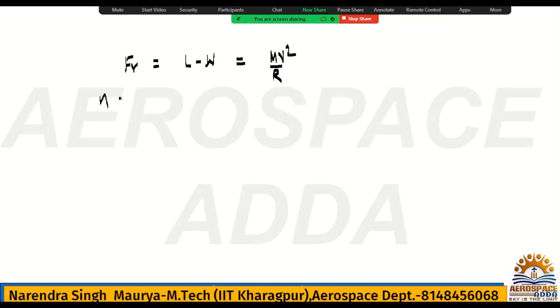What is the load factor N? Load factor N, definitely it will be lift by weight, and that will be greater than 1. In turning flight, I told you, load factor will be greater than 1. So what is L? L will be N times weight. This is the lift force.